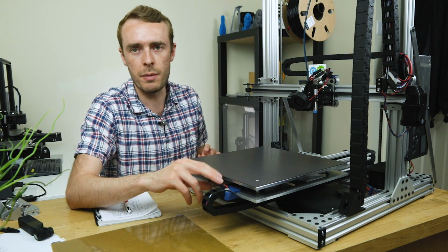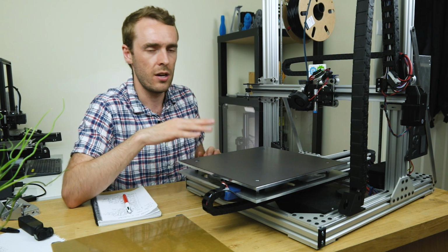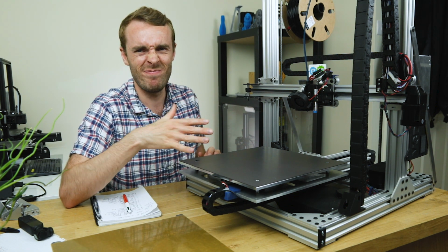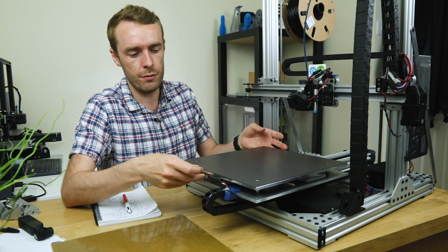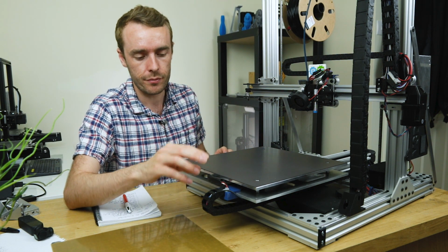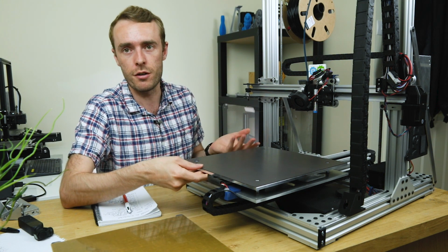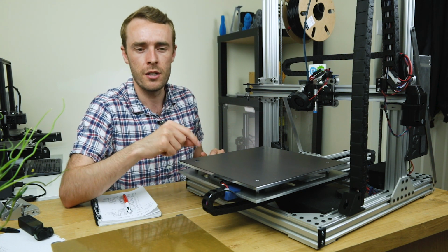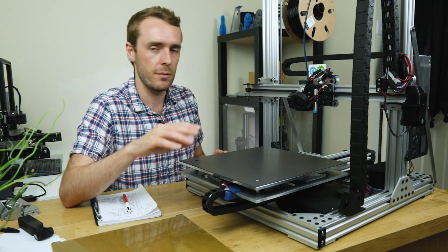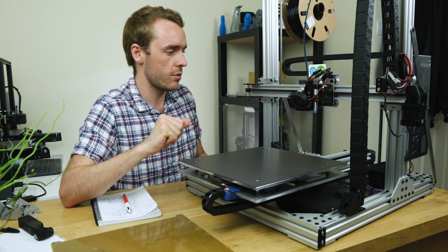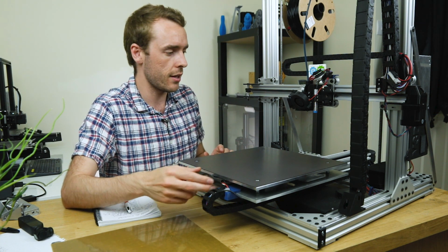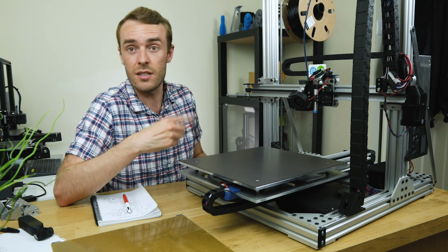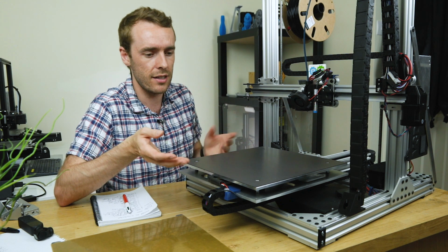Of course it is mains powered, which I do prefer generally on printers now, maybe apart from the ones from China, just in case the quality is not so good. But for me to do one myself, definitely prefer mains powered beds. The nice thing is that for that 450 watts that I've got and 240 volts, it means the current is only 2 amps. So you can use a fairly thin gauge wire. I mean, don't go too thin, you don't want to screw yourself over, but you can have a fairly thin gauge wire. This might not be true, but I feel like it would be safer because the current is lower. It's still the mains, so definitely some added danger there.